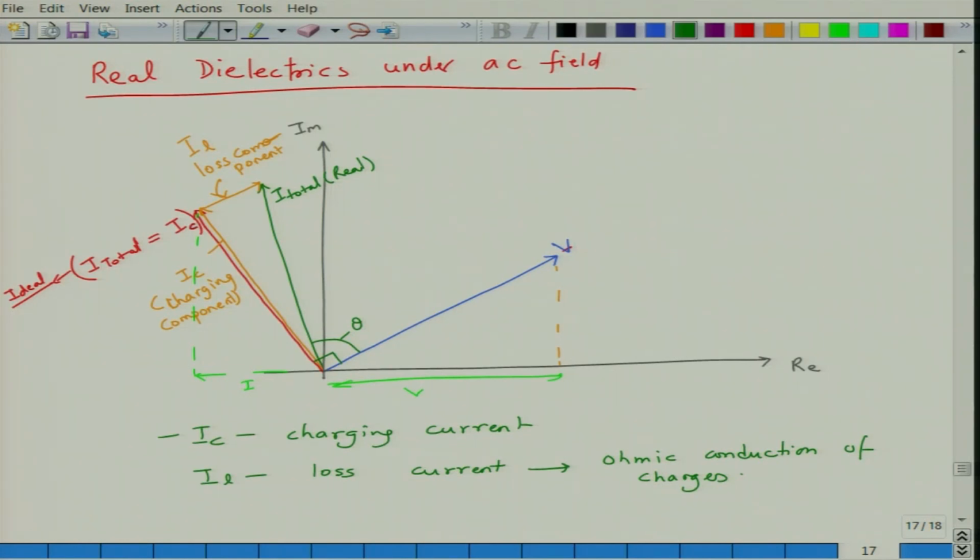Generally the ohmic component of the loss is depicted as a frequency independent component of loss, but in addition there is a possibility of frequency dependent losses, such as dipoles rotating in a system. When the dipoles rotate in the system, they consume energy. You may have traps or defective charges in the system which may keep the dipoles bound.